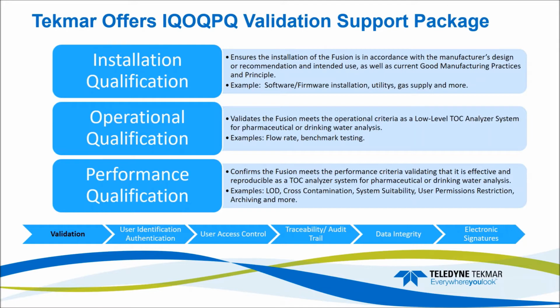For your IQ, we ensure that the installation of Fusion is in accordance with the manufacturer's design recommendations for its intended use, as well as current good manufacturing practices and principles. We're going to make sure everything's installed correctly, including your nitrogen gas supply, all that kind of stuff. Then for operational qualification, you validate that it operates correctly as a low-level TOC analyzer system for pharmaceutical and drinking water analysis. We'll check things like flow rate and benchmarking.